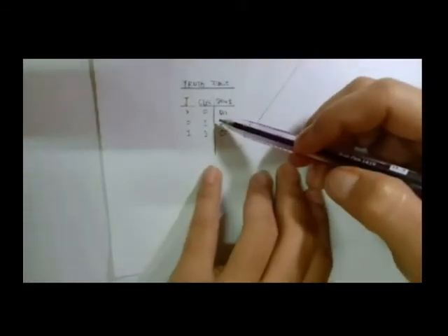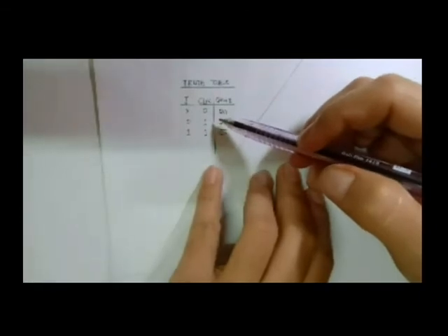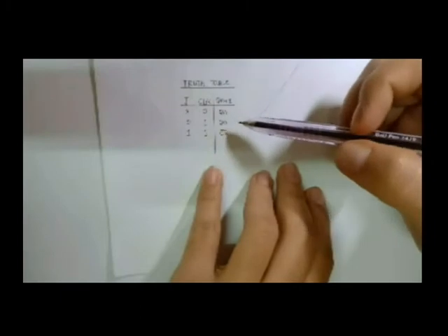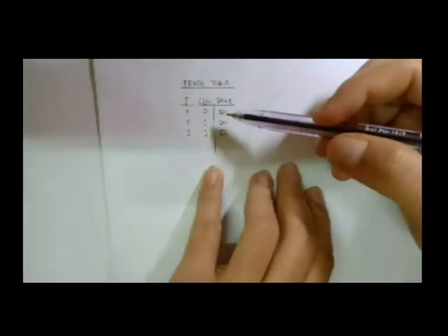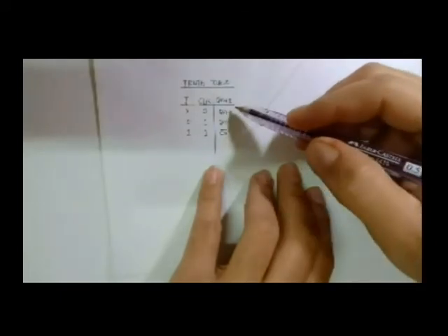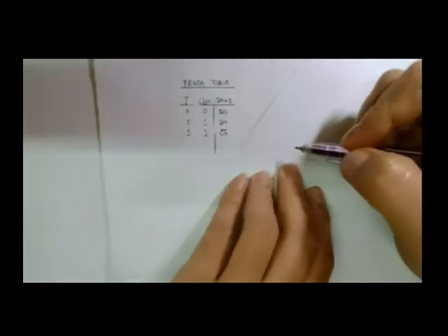So next is the truth table. If the clock is 0, that means that there is no clock pulse transition. And if the T is X, X means that either 0 or 1 is a valid value. So the output is Qn. That means hold.